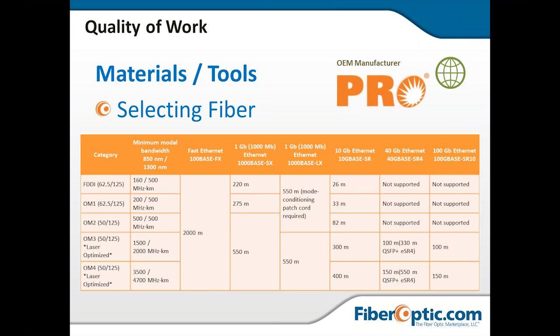And this one specifically here is not going to show us the single mode because this is just a chart on the wavelengths for multi-mode 850 and 1300. But you need to look hard at the budget and say, okay, we're going to need to start to move up and have some OM3 or OM4 installed, or we're going to have to go single mode. Universities, obviously you have students. Hospitals, it's the X-ray and MRIs and all the other stuff that's going over the networks that are really causing a tremendous amount of bandwidth limitations, and therefore they need to up those.